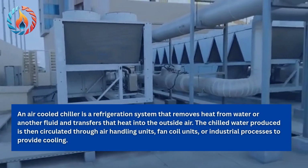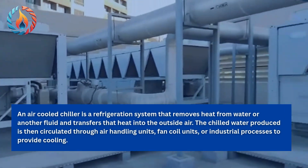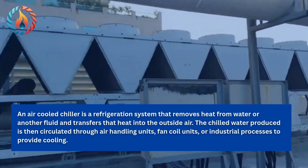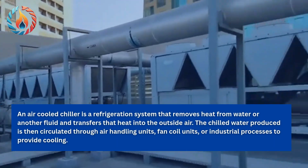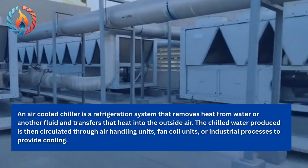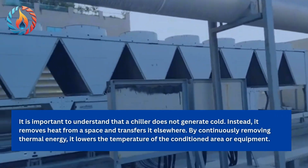An air-cooled chiller is a refrigeration system that removes heat from water or another fluid and transfers that heat into the outside air. The chilled water produced is then circulated through air handling units, fan coil units, or industrial processes to provide cooling. It is important to understand that a chiller does not generate cold.